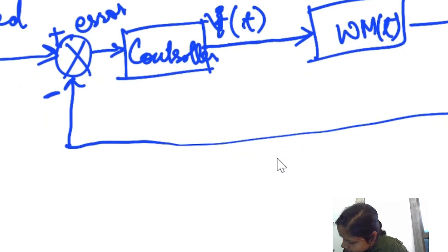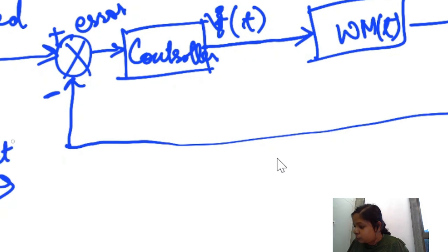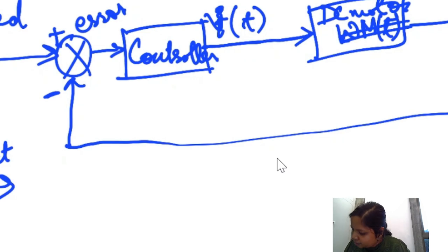So what really happens is you always have some reference input. It could be a speed. Let's say this was not a washing machine and this was a DC motor, and you wanted some speed of the motor. Right now this is the speed of the motor, it is coming out as something. My reference speed, I said that I want 1500 rpm. So it is going to take the speed output that comes in the feedback. Let's say at some point it was 1200 rpm. It is going to take the speed 1500 rpm that is already there, find out the error.